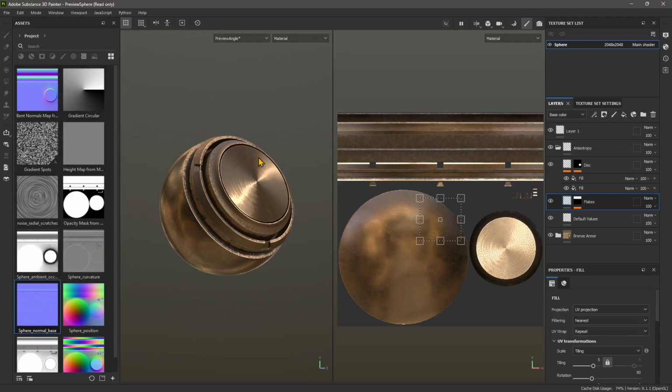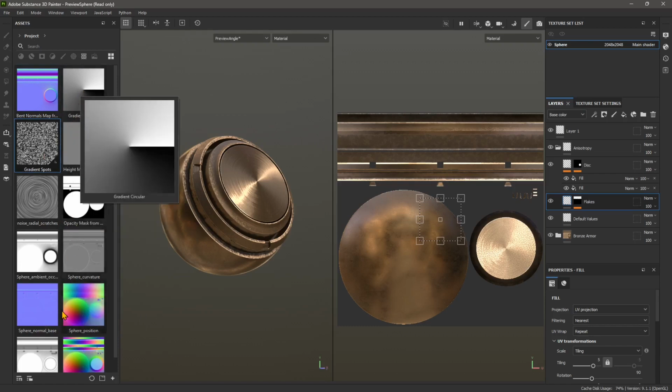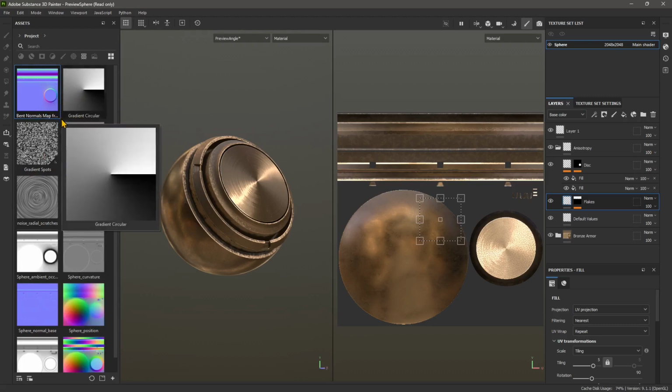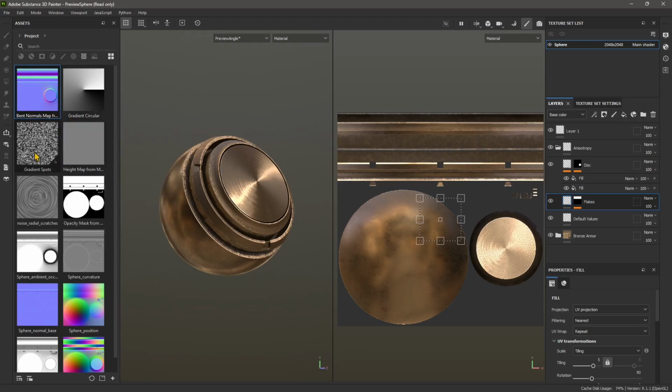Essentially, you have the possibility to apply to your 3D objects different materials, different maps, different effects, and you have essentially two ways you can apply textures. You have tileable textures and non-tileable textures. Tileable textures are similar to this one, so you can repeat them many times on a surface, while non-tileable textures are usually the unwrap textures or unwrap maps that can only be placed in specific points of the 3D model. And then you also have some other type of texture like the environments that can be placed outside the model, and they will help you to generate reflections, for example, on metallic objects, and also lighting.